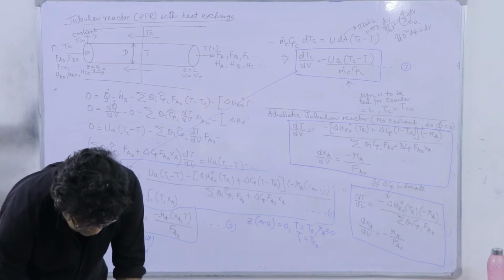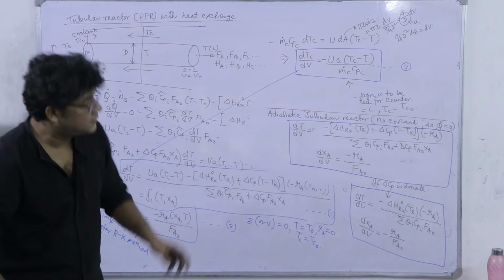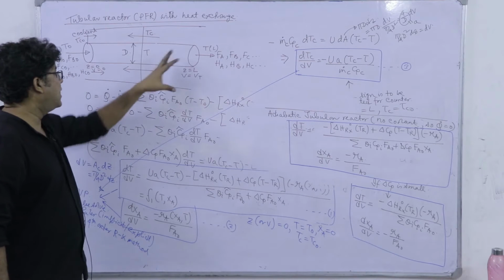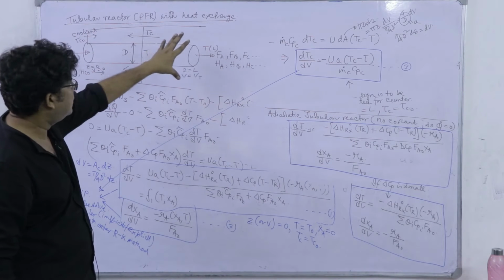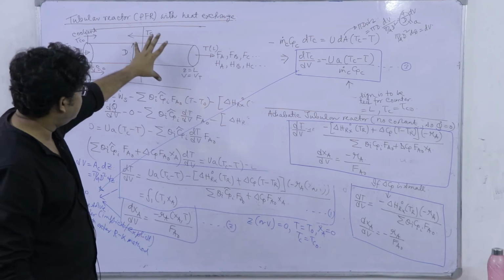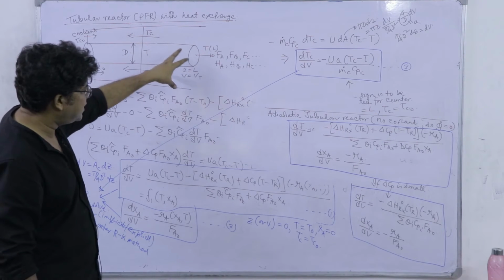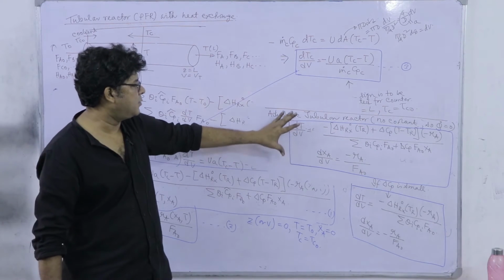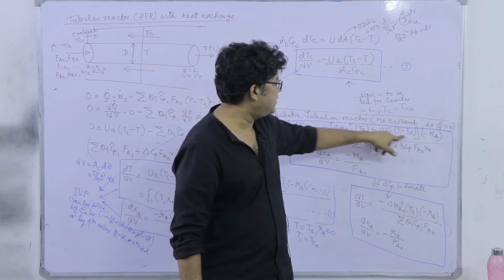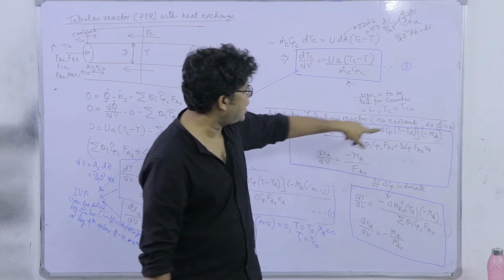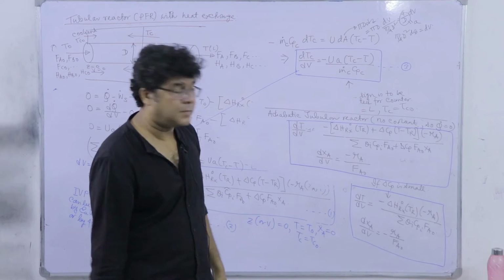And additionally, we have discussed the coolant's effect, the non-adiabatic, non-isothermal case, that is the primary one. We started our analysis with that, and from there we simplified it to adiabatic and further simplified where the contribution of change of temperature from the reference temperature in the overall heat of reaction is negligibly small compared to the standard heat of reaction at the reference temperature.